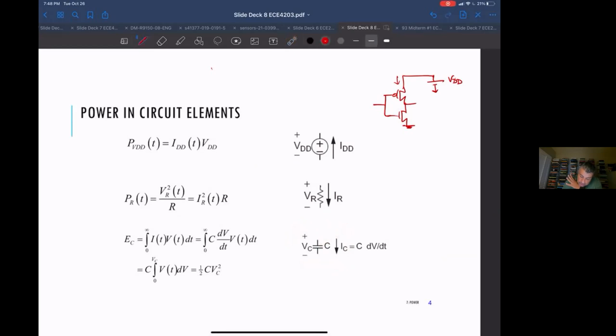Okay, so let's look at the different ways to look at this thing. So Q is equal to CV for a capacitor. This is the charge, this is a voltage, this is a capacitance. So if you look at the voltage, it really depends on how much charge you've put on this capacitor. And basically the rate of change of this voltage, dV/dt, is dQ/dt over C. So dQ/dt is current, so dV/dt is I over C. Or this says the reverse of this.